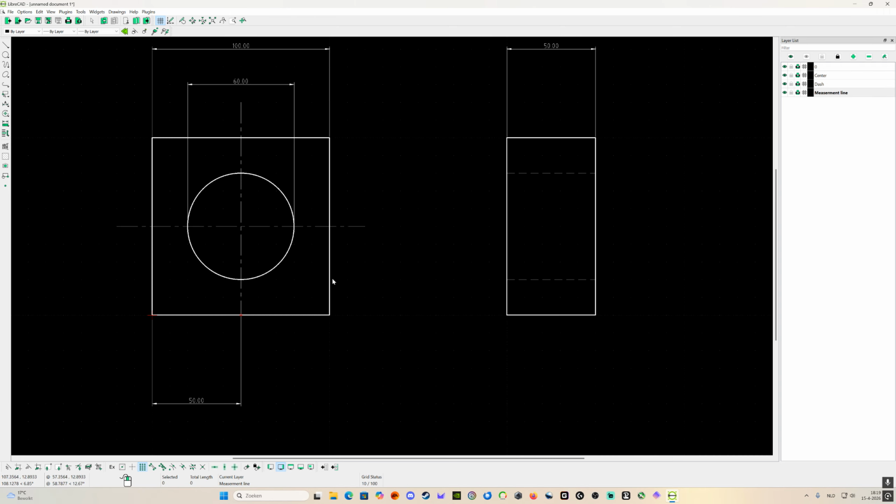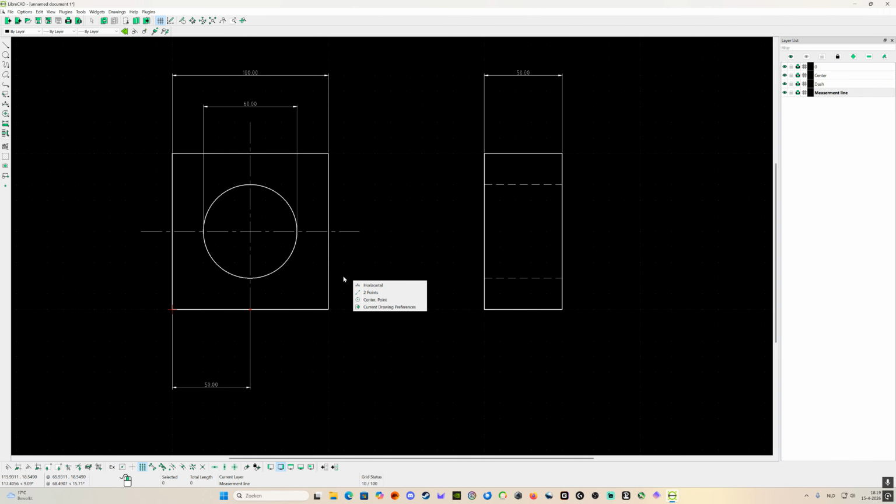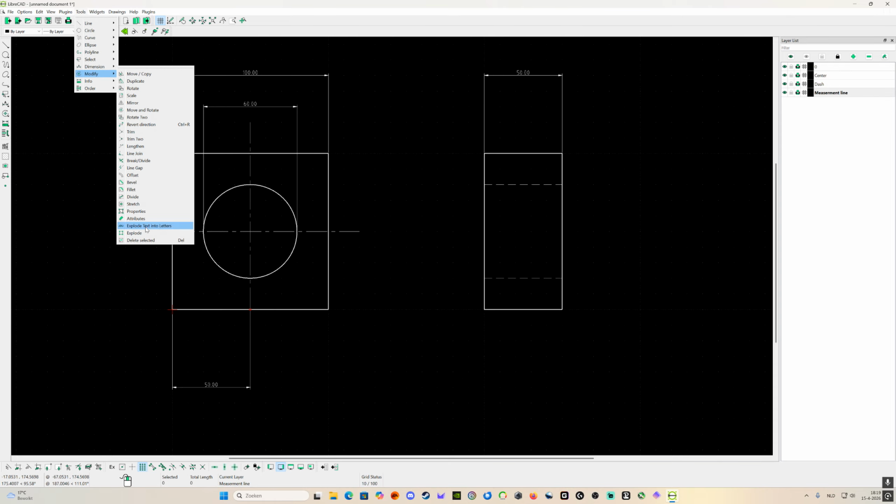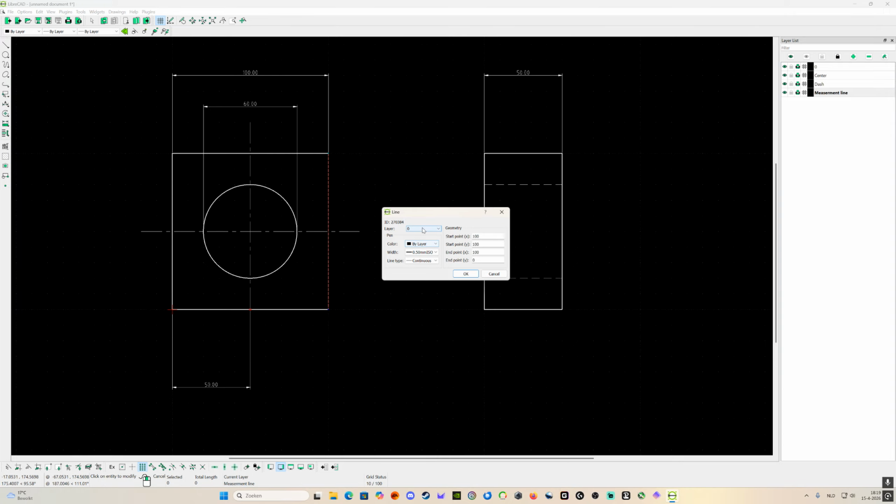Just click this. If you want to change one line, like that one, and I said, okay, then you go to Tools, you go to Modify, and you go into Properties, and then you can select that one. You said, okay, but this property I want to have dash. And if you click it now, that's a little bit strange because dash, and then you must click this one also by layer, continuous. The strange thing is that I got a new version of LibreCAD now. In the old version, when you change this, the line will change, but not now. Yeah, by layer, that's good.